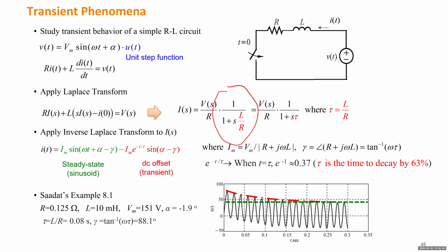So for this case, the voltage will have an instantaneous change, and then we'll call the delayed change on the current. That delay can be modeled by this first order system with some time constant. So then we move to the equivalent circuit of the generator. When we open the circuit, the current has an instantaneous change and the flux has a delayed change. And we just figure out what that delay is. That will give us some time constant.